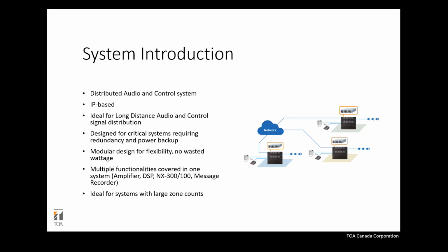audio and control signals. It's designed for critical systems requiring redundancy and power backup. So the VX3000 is designed with battery backup in mind, redundancies in mind, and reporting in mind. There's fault detection in the system, and since it's already tied to the IT system, you can configure it to send an email or alarm and notification should any system fail or there's a shutdown happening.